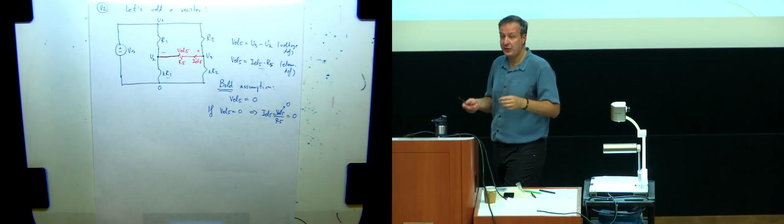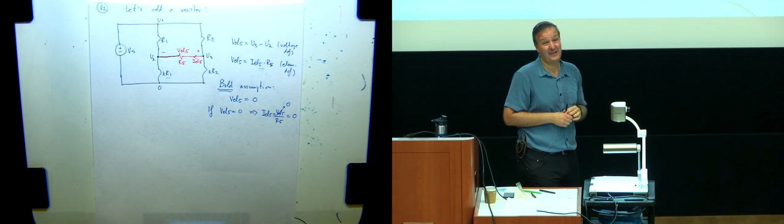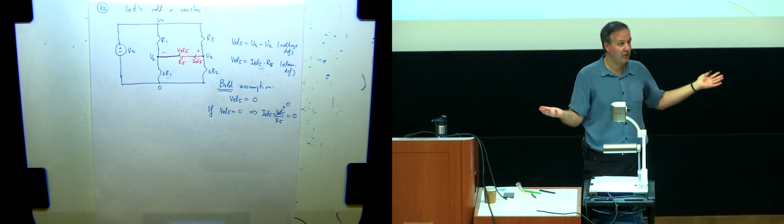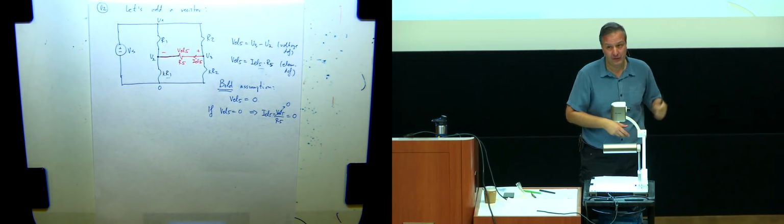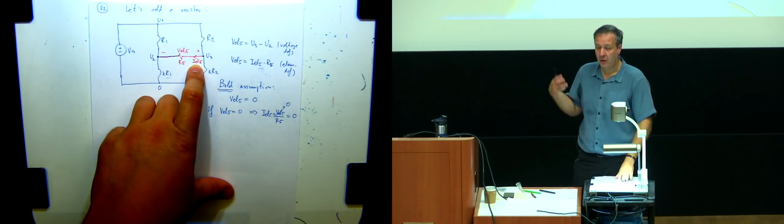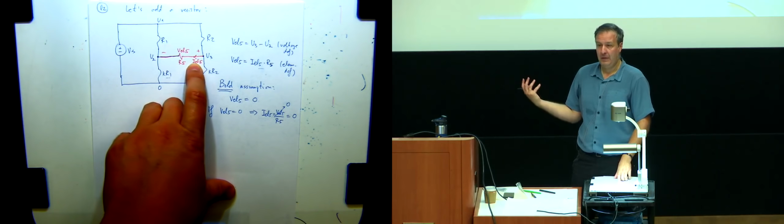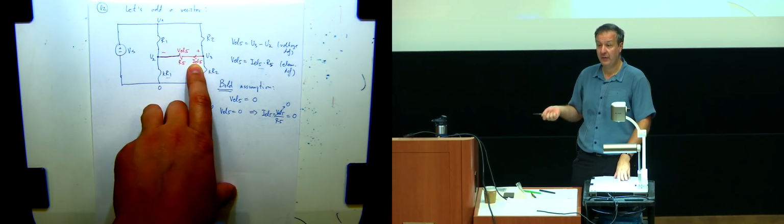Right, open circuit, by definition, has no current flowing through it. So I element is zero, and voltage can be whatever is set by the outside circuitry. So if indeed the element current is zero, I can just pretend this is an open circuit and pull it out.